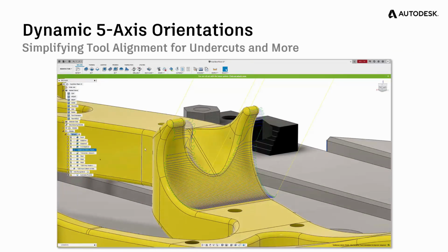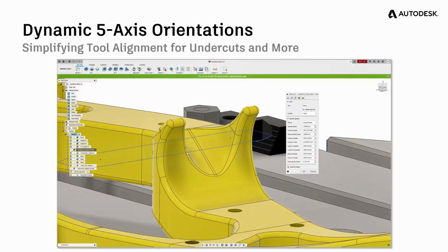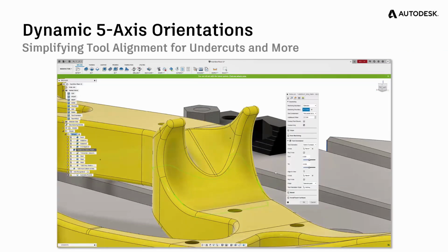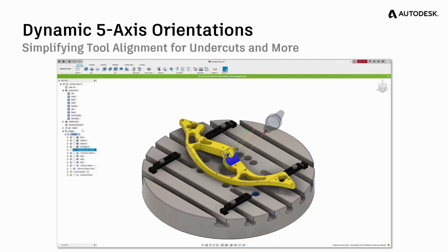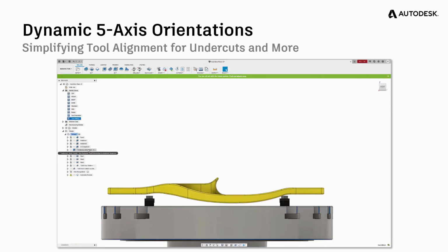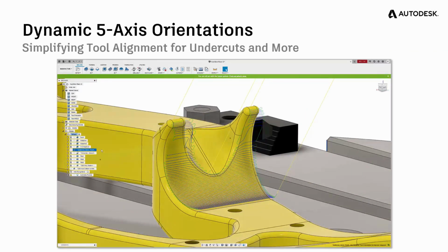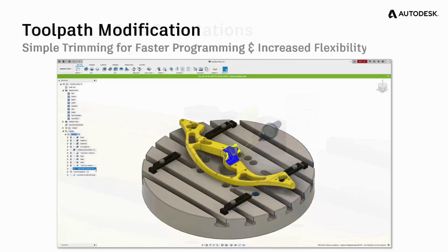We've also improved the 5-axis programming capabilities of Fusion 360 with some more tools that have originated from PowerMill. Now, this video shows development work that allows the 5-axis orientation of the cutting tool to be defined interactively. So you can see in a moment that we'll be able to display an XYZ coordinate system. You can see that appearing on screen now. And then dynamic drag handles can be used to drag the cutting tool into a different rotated position, allowing you to optimize the rotation of the machine tool to machine undercuts more easily, explore using shorter, more rigid cutting tool assemblies, just basically improve the way you machine with your 5-axis machine capabilities. So this is great for 3+1, great for 3+2 machining, as well as 5-axis machining more broadly.